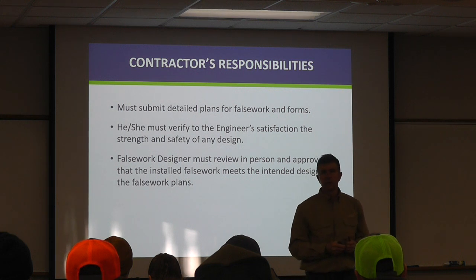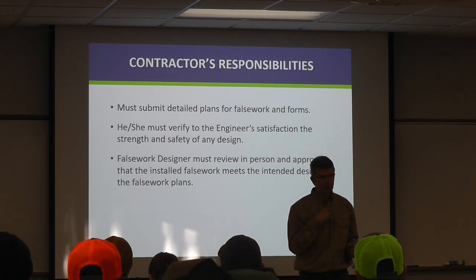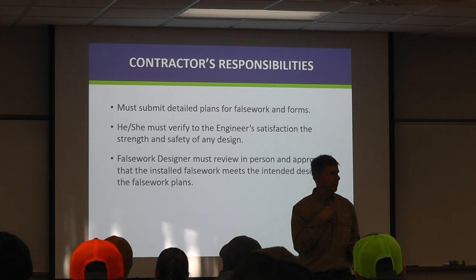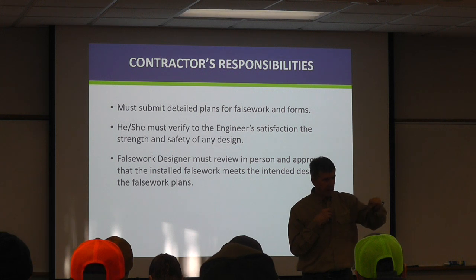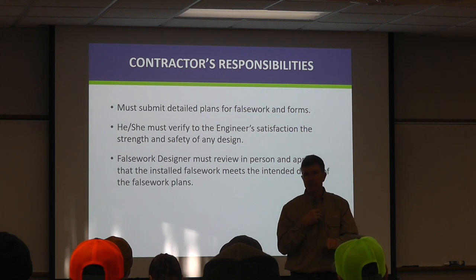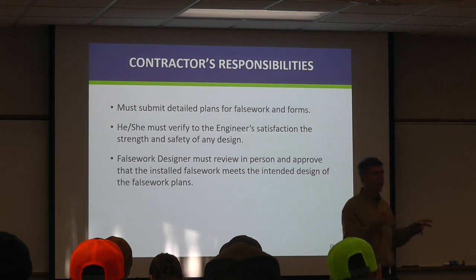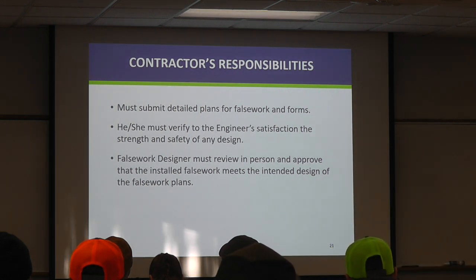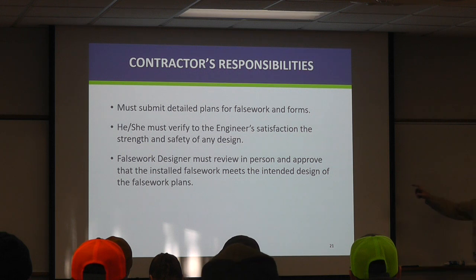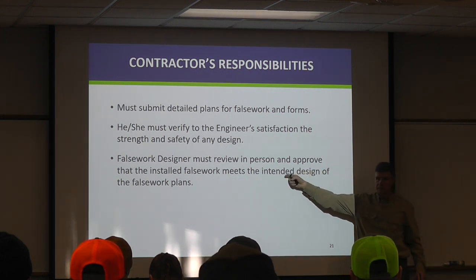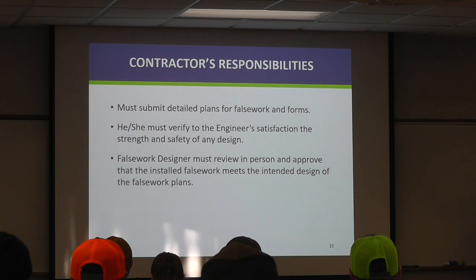And so we think, just as engineers, if the engineer who designed it had been out there and said, okay, load path coming down, well, look at this, load path is coming through this little member and there's no stiffeners. It would have been a fix: you could have welded a stiffener on. You could have even put timber blocking in as a stiffener. But I recite that for this reason: don't take this part lightly. The falsework designer has to come out and approve in writing. Visit the site, approve in writing that yes, this is what I intended.